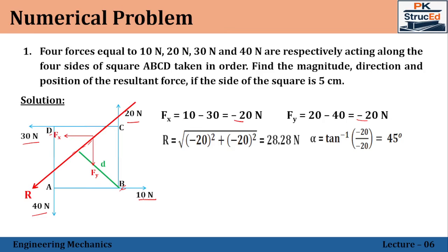We'll start with the 10 Newton force. Here you can see the 10 Newton force is acting at the point B itself. Since it is acting at that point itself, this 10 Newton force will not create any moment. Now going on with the 20 Newton force.